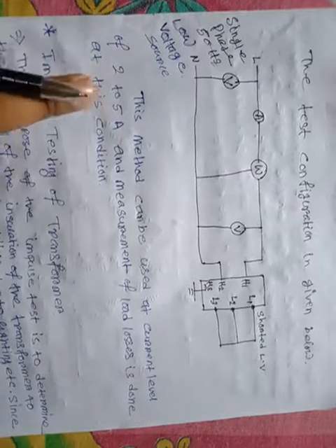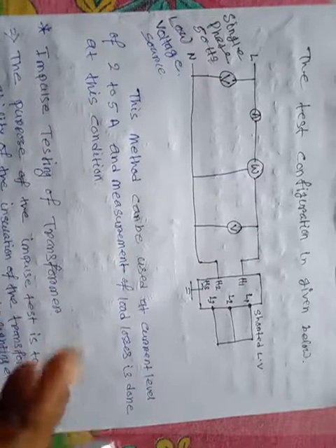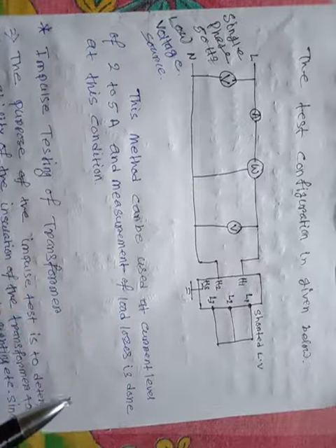This method can be used at a current level of 2 to 5 ampere, and measurement of load loss is done at this condition. This circuit is like a short circuit.